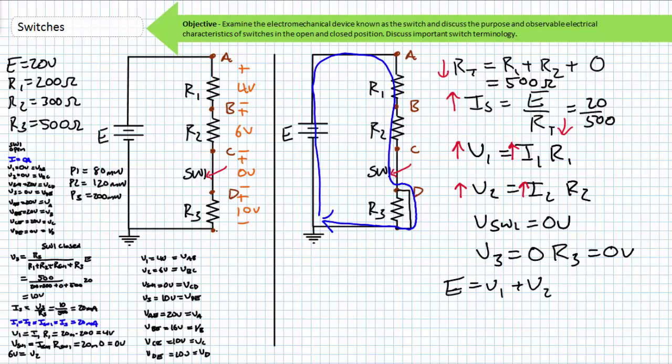With reduced total resistance, source current should rise. We should expect approximately 40 milliamperes of current flowing through this circuit with a shorted R3. Double the current because our resistance dropped in half. Given power is a geometric function of current, start thinking now of how hot these remaining resistors are getting. With increased current draw through our remaining resistors, we should expect a larger voltage drop across them.